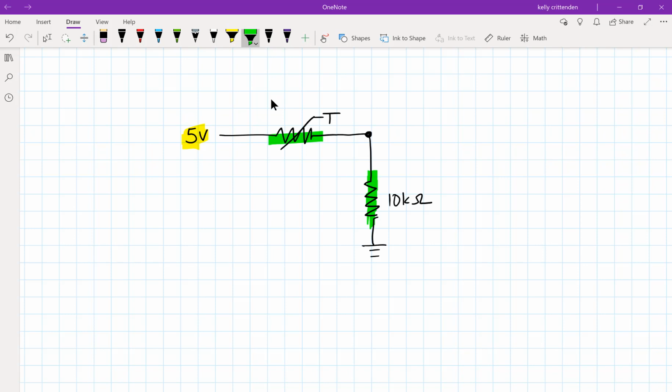So we're measuring right here. So we have tapped into this node with, well, I'll put an orange wire on mine, I'll put it red here, with a wire that goes over to pin A1, so analog read 1 on our Arduino. And we're measuring from there to ground, basically. So this potential, that's the voltage that we're actually measuring, the voltage in that 10,000 ohm resistor.